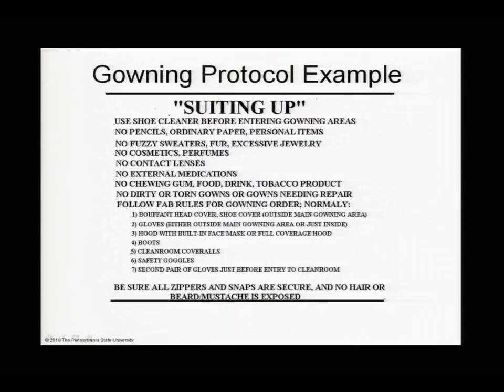So when you're suiting up, this is the sequence. Put the shoe liner, the shoe covering, on first. You have to make sure that you don't have any personal items. Don't want any fuzzy sweaters or fur or jewelry. Like to keep the jewelry down. No cosmetics, no perfumes. We talked about aerosols several times. Contact lenses.